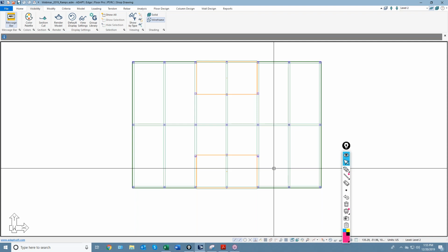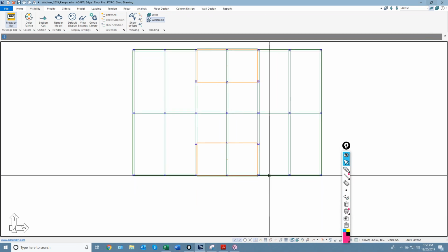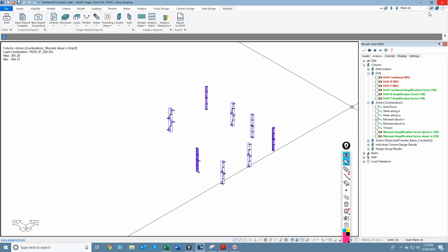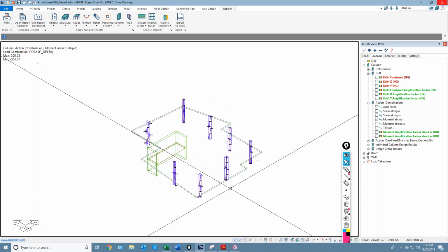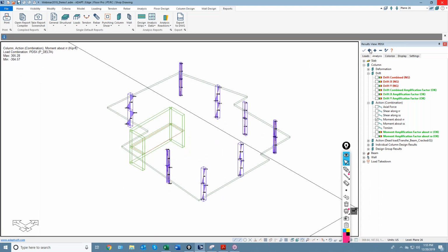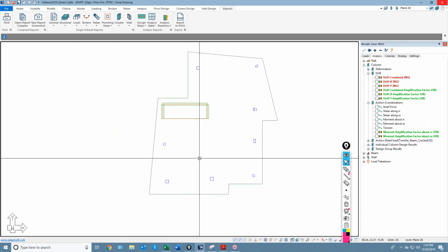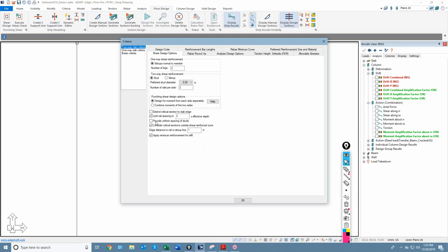We're going to move over now to punching shear. So for ACI, specifically for ACI, if I go back to my other model, let's go to this two-way slab model, and let me turn off some of these options for display. Okay, we'll take this level, for example. If we go over to floor design, shear design, there's two new options, or actually three, that have been added.